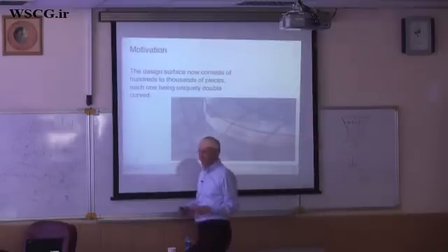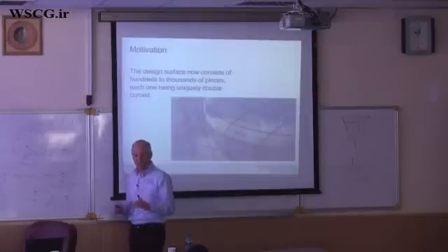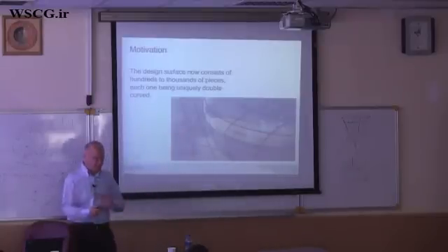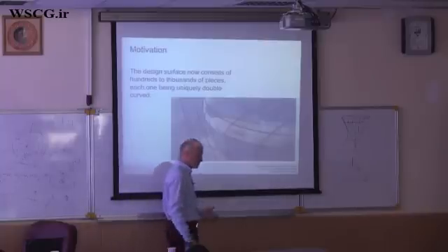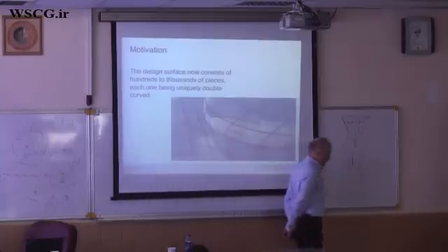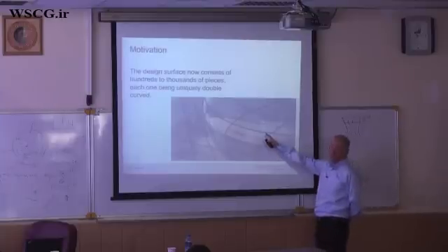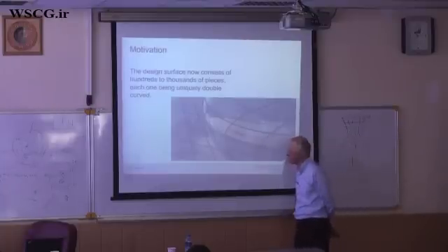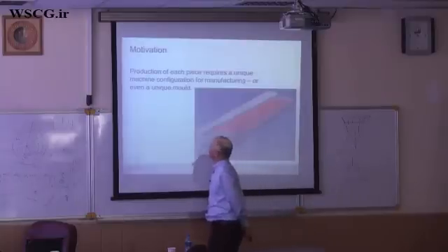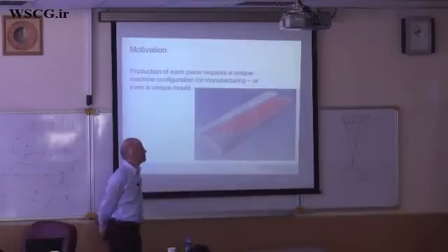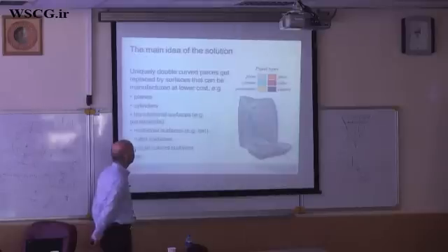In general, it will be, as we say, double curved, so not developable and curved, so both directions curved, both principal curvatures not zero. So this will, in most cases, require the making of a mold, and the making of a mold is typically more expensive than the actual production of the panel using this mold. So this is out of the game somehow. You cannot do it. So what can we do?